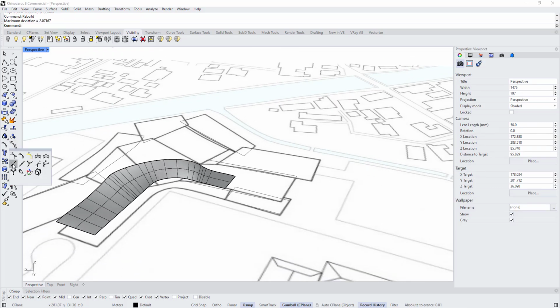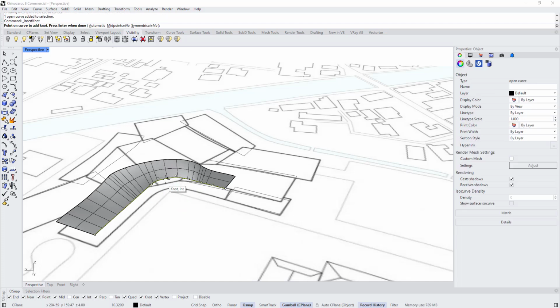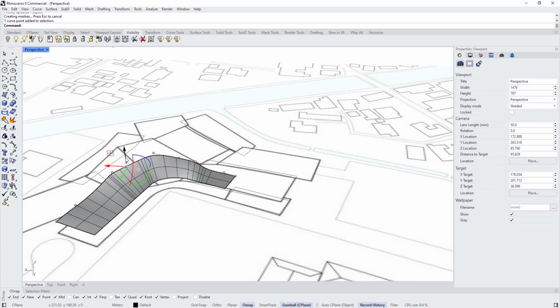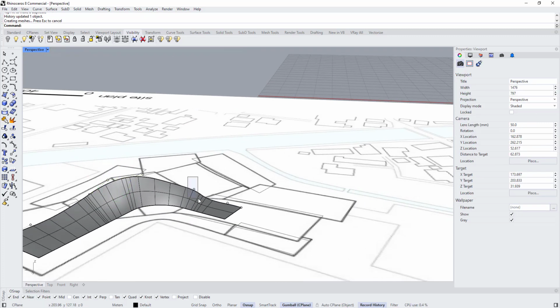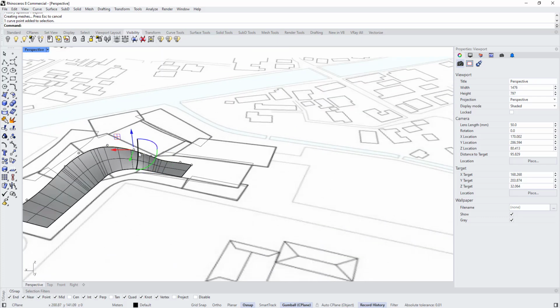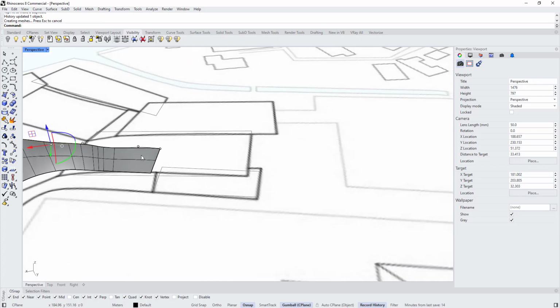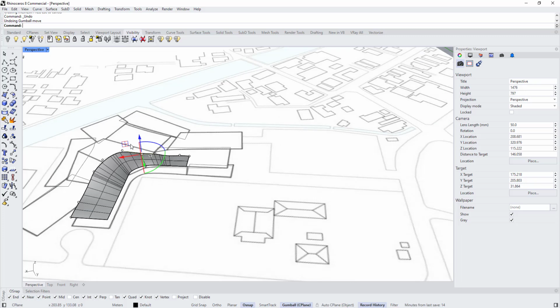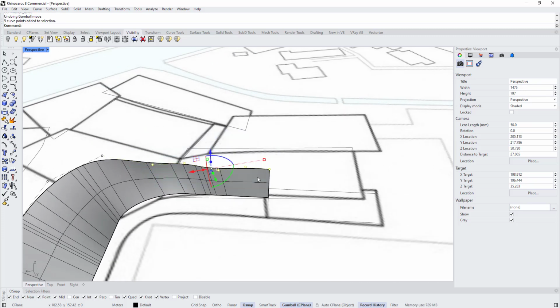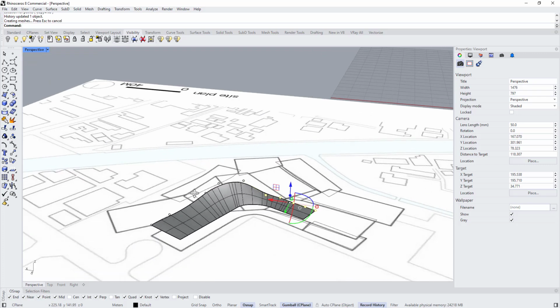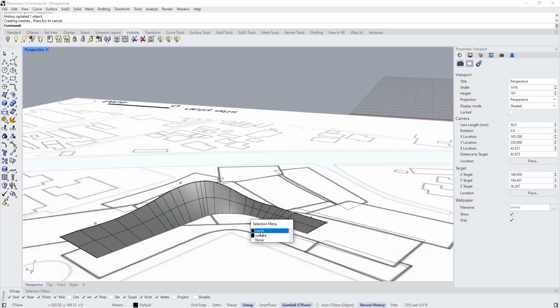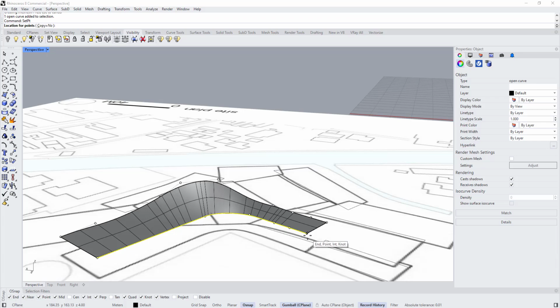Let's start adding nodes. So let's add a point here, here, and here. Maybe they are the same thing. So now I can start adjusting the curve more to match the design requirements. Let's select all of this. Let's select all of these points and type set point and set it to Z and align all of them here. Let's select this curve and type set point to Z2.